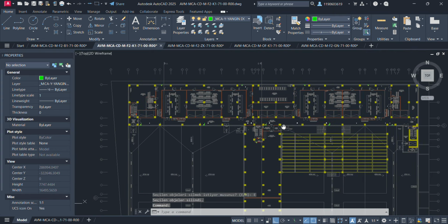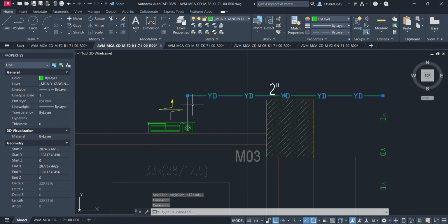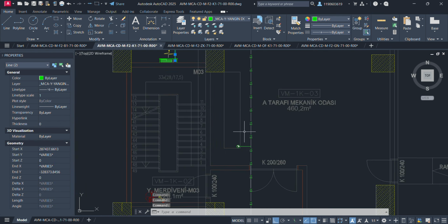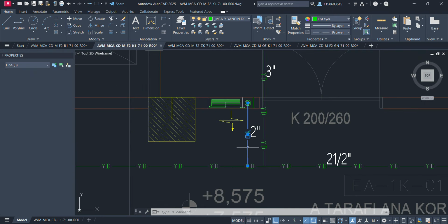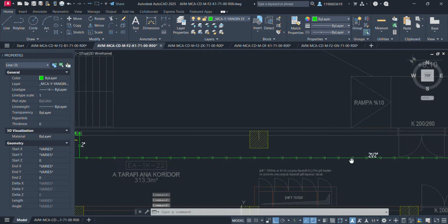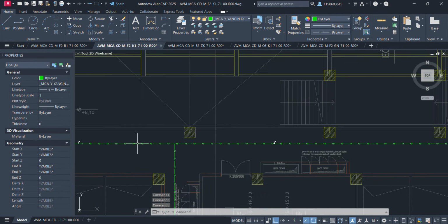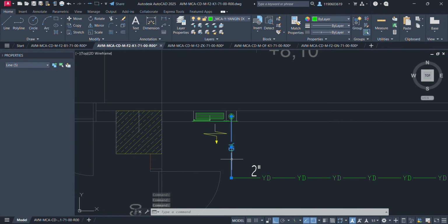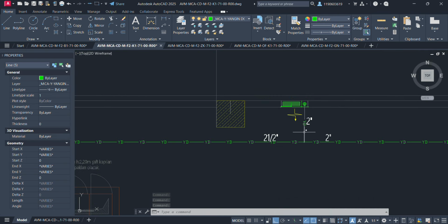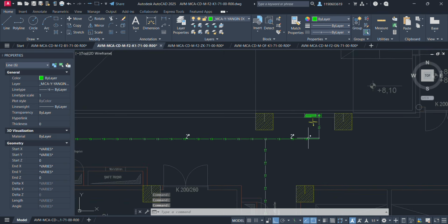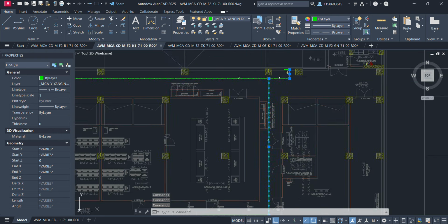Sanitary systems include sewer pipes, lift stations, and water treatment systems. Designing sanitary systems requires great precision, as pipe sizes are determined based on the population of the area or the size of the facility. Additionally, elevations and slopes must be considered to ensure that water flows smoothly and naturally. The system's components also include treatment plants, which play a key role in purifying water before it is released back into the environment, as well as safe disposal systems for treated water.